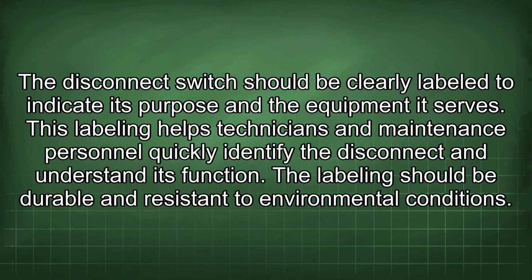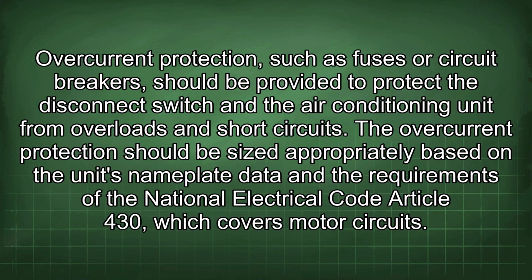This labeling helps technicians and maintenance personnel quickly identify the disconnect and understand its function. The labeling should be durable and resistant to environmental conditions. Overcurrent protection, such as fuses or circuit breakers, should be provided to protect the disconnect switch in the air conditioning unit from overloads and short circuits.